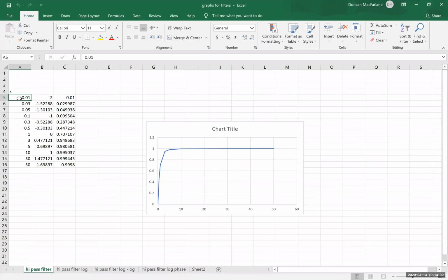And whenever you can write something as a dimensionless quantity, you're one step ahead of the game. And so this omega RC coming out as such an obvious dimensionless number allows me not to worry about kilohertz. It allows me not to worry about mega ohms or microfarads.